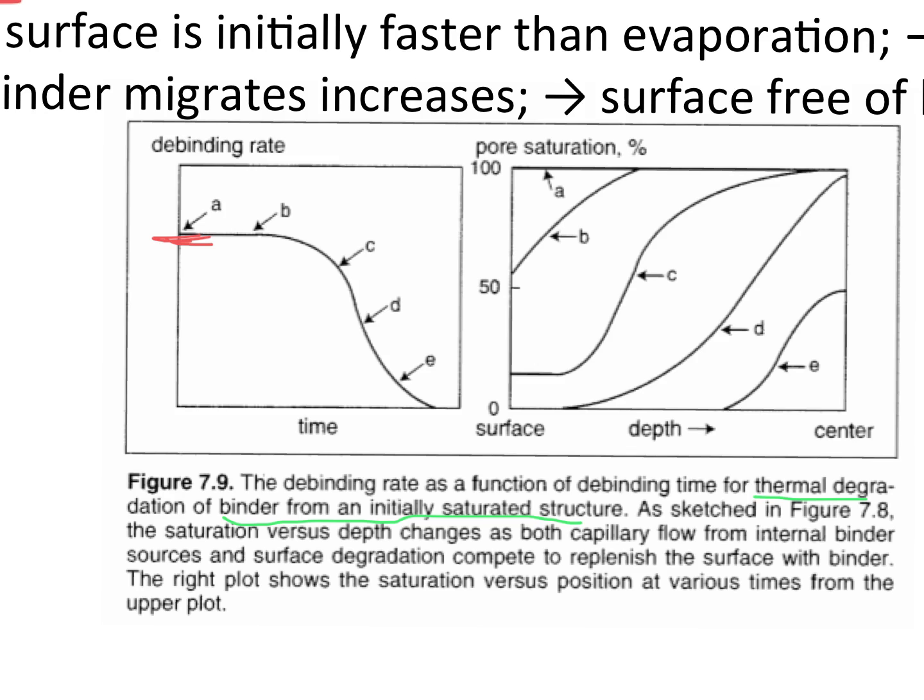We plunge below the surface. We still have a lot of vapor transport, so the rate of debinding is still relatively high, but then as we start to get down below the surface, it slows down because diffusion is now controlling this overall process. We've removed the easily removed stuff at the surface, and now what is still left has to turn into vapor, and that vapor has to slowly make its way out of the compact. So we slow down the overall process and then continually remove this, eventually to the point at which zero binder is left behind.